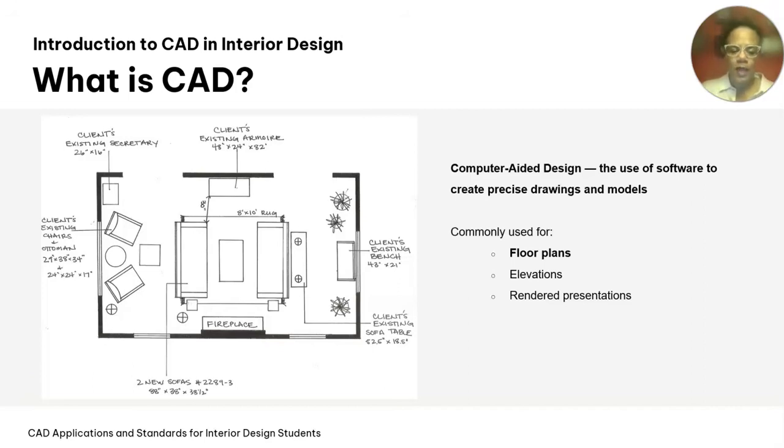And so a floor plan, I like to just describe it as taking a buzz saw and just cutting right across a room at 4 feet. So all drawings are cut basically at 4 feet. And then once you've gone all the way around the room, you lift the top of that space up, you move it over, you look down, and that's basically what a floor plan is.